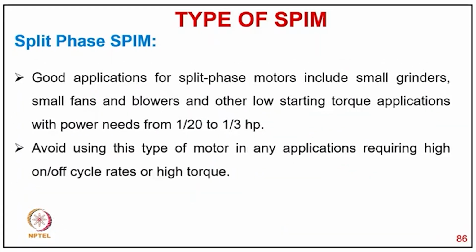Good applications for the split phase motor include small grinders, small fan blowers, and other low starting torque applications with power needs of 1/20 to 1/3 horsepower. Avoid using this type of motor in applications requiring high on-off cycle rates or high torque.